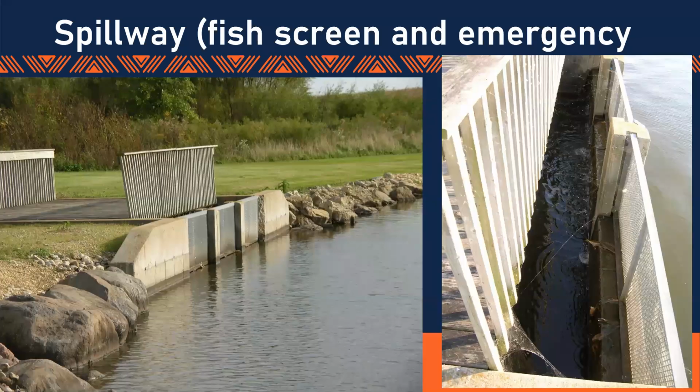Here's a little bit better shot of the same setup. You see the walkover bridge, drive-over bridge for the lawnmowers and the light equipment. But on the right-hand side, you see the concrete weir, basically the top of the dam, where the spillway is catching water and flowing it over, with the screen setting there, and you've got this large volume that's capable of handling all the water. Should it get a large rainfall event, a large slug of water coming towards it, it's got a place to go.